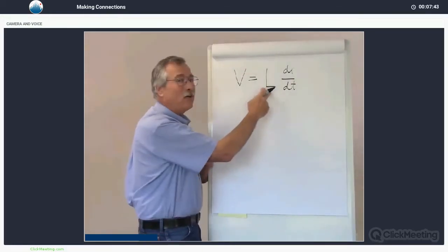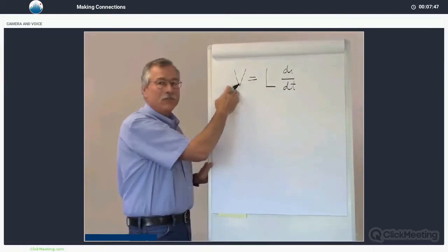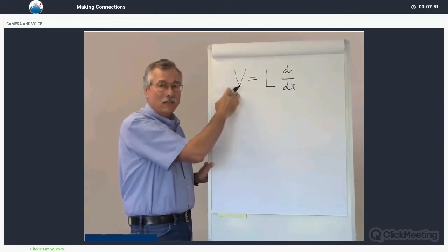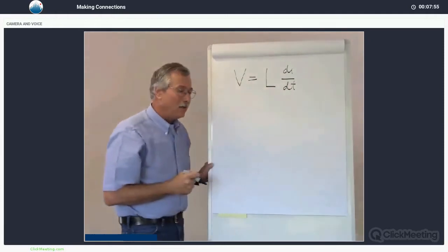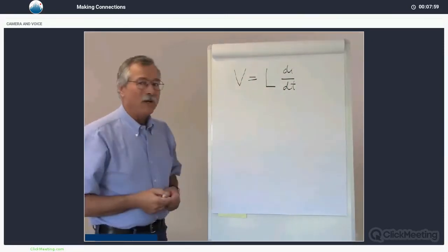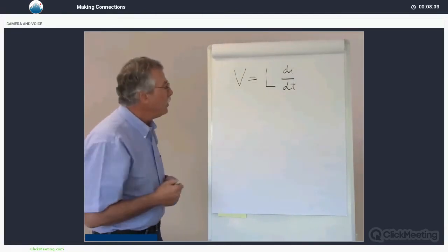It only takes a few nanohenries of inductance, as you can see, to give us volts of reverse EMF. And we're dealing with laser diodes that only need a couple of volts to operate on, so this ends up being a key item. So why do we care about inductance and talk about laser diodes and interconnections?